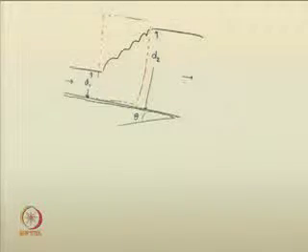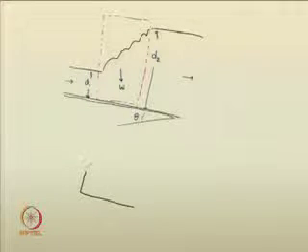So, you have seen the solutions of the last day's quiz. Now, coming back to hydraulic jumps in sloping channels. As we can see from a side section, the weight of the water in the jump is significant, as you can see here. I am describing a control volume given in the red color here. That control volume, if you take into account the control surfaces, I am just taking the control volume.